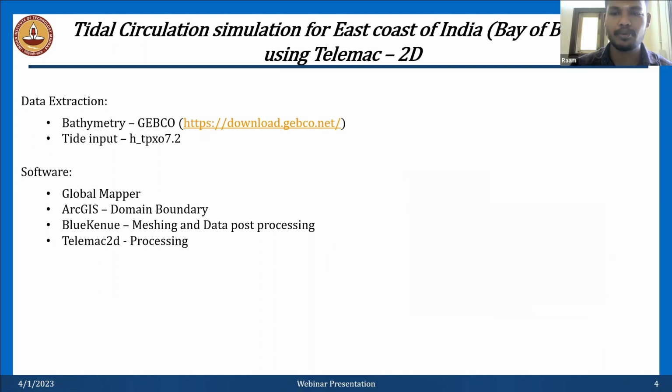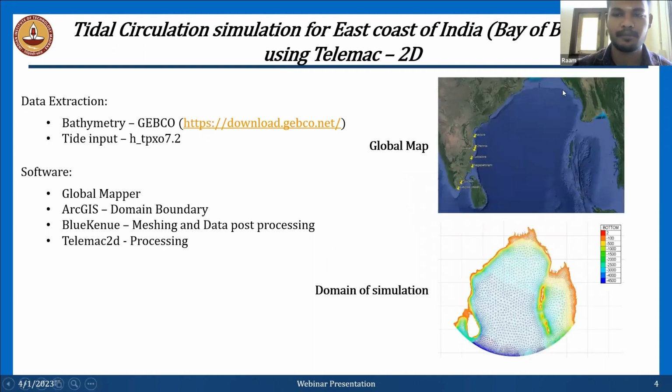Then Blue Kenue is a software where we will create the mesh and import the bathymetry over the mesh. These are the meshes. From this outer boundary we will give the input as a tidal input, and it has to be simulated over the region.